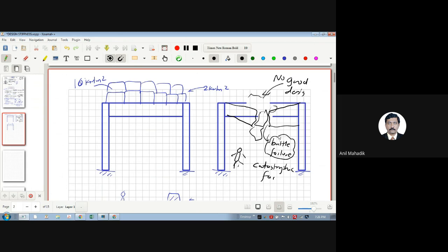So it happens if there is not enough reinforcement within the structure. All of you know that concrete is a brittle material, and if you are not providing enough reinforcement, then it will collapse, because there will be shear failure. Generally the brittle failure is a shear failure due to excess shear force, and there is no ductility, because all of you know that whenever you put adequate reinforcement in any concrete structure, it is ductile in nature.